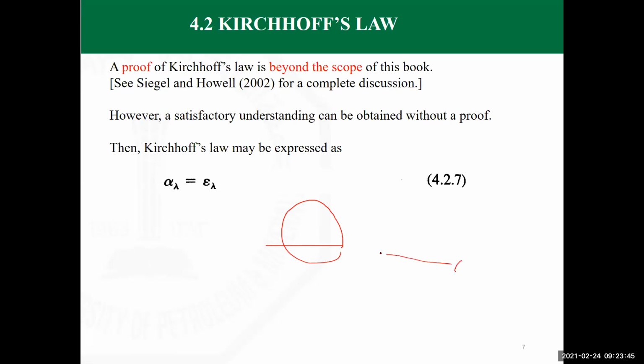this source may have a ray that's going to enter here. When it enters, it will be reflected like that, and then reflected here, and then here, and then here, which means that in most cases it will not leave the surface. So the emitted energy has all been absorbed, even if this body is not a black body. So that was a thought experiment to show that epsilon and alpha could be the same.